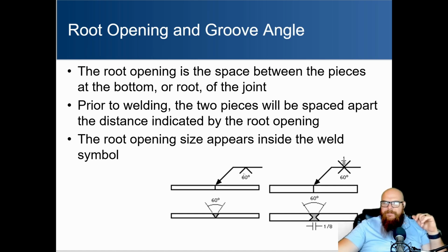So it's kind of a little bit opposite in this situation, where it looks like it might be done underneath here, but because the arrow is touching the top and the markings are underneath the reference line, you're going to want to do it actually on the top.